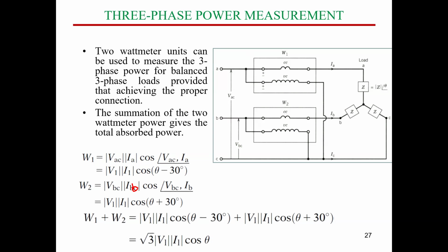So simply, I'm going to say firstly, this is an A, B, C system. This is a positive system, positive sequence system. I will have 2 wattmeters. The first wattmeter is going to be connected between, or to measure, phase A current and the volt of A and C. So W1 is going to be the negative sequence, and W2 is going to be the positive sequence wattmeter.